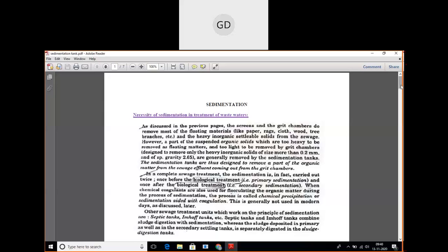So here also, similarly, like in raw water engineering, we keep it for a certain period of time, a detention period, and after that the materials settle automatically, isn't it? Here also it is similar. Also, the shape and size of the materials can be changed by using some chemicals, and those chemicals are known as coagulants, as we already learned in your raw water engineering.